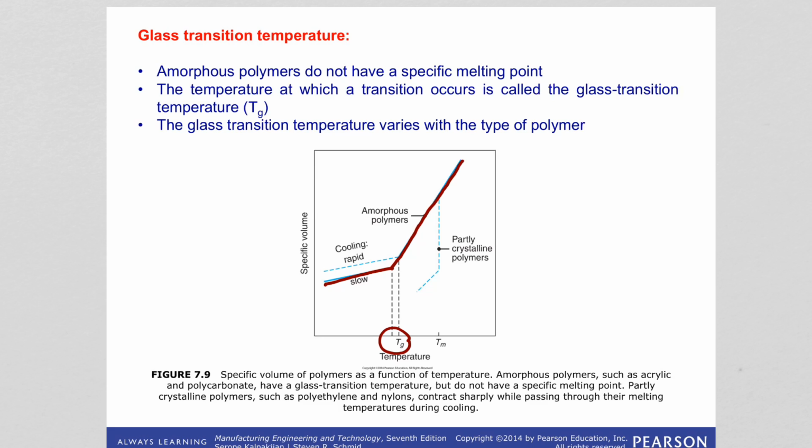Actually, if you guys remember, there was the Challenger space shuttle disaster. Why did it happen? Because the rubber normally can act as a seal because of its rubbery behavior, but at the time of the launch, that day, it was cold temperatures, and it went below the glass transition, and the material was behaving brittle, so it didn't seal, and that's why the catastrophe happened.